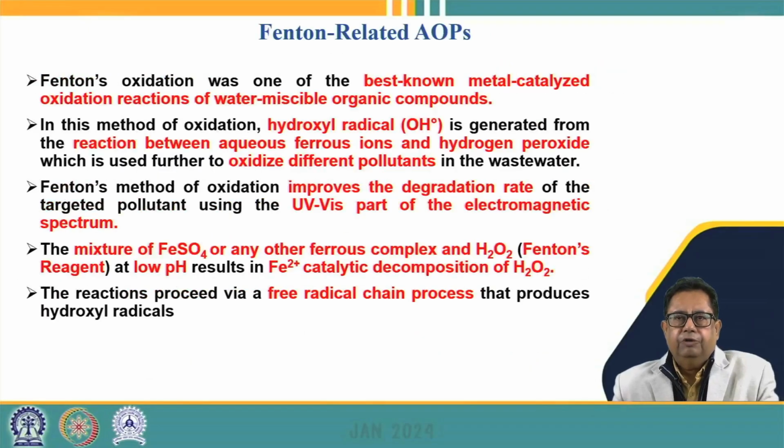Similarly, we can have the Fenton-related advanced oxidation processes, where Fenton's oxidation is one of the best known metal catalyzed oxidation reactions of the water miscible organic compounds, which are the targeted compounds here. So they can be oxidized by using Fenton's reactions. In Fenton's reaction, the hydroxyl radical is generated by the reaction between ferrous ions and hydrogen peroxide. The reaction of ferrous ions and hydrogen peroxide may result in the formation of dot OH radicals, and that can oxidize different types of pollutants which are present in the wastewater.